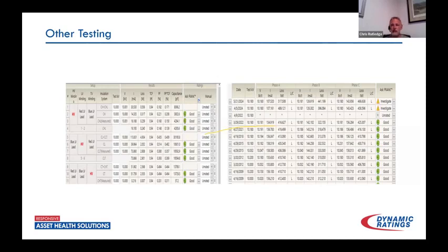And sadly, they did not provide me with a power factor through each test. So my suspicion is this is an odd tap. So that PA would be in series with this testing. And so, if we've had some type of failure of that PA on this phase, then we would see what we're seeing here. I would really need to see some tests on the even taps of this transformer, or test through every tap to have a comparison to see how this excitation current changes.